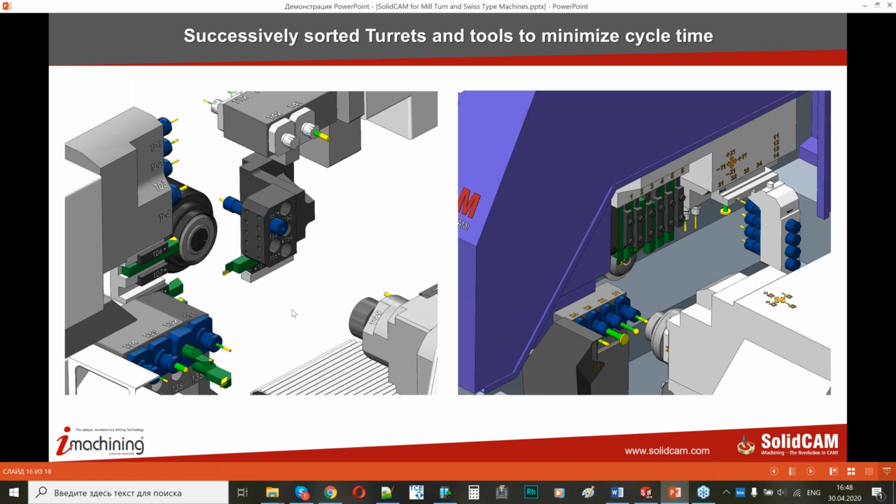If in the previous machine, the mill turn machine, we had a maximum of 3 turrets, here we can see a lot of tool blocks, sorted into mills and turns, even with B-axis, index or simultaneous. There is also a possibility to change the tool block attachments.